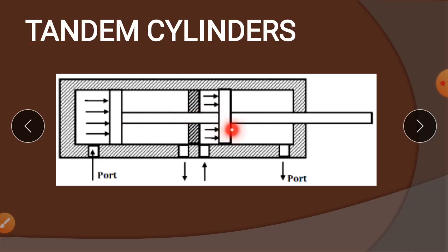So it is connected, one piston rod is connected to another piston rod, but there is some restriction between, there is some blocking between the two piston operations. Okay, so you can also say the two cylinders are going to be connected in this way. Each cylinder has two ports, one inlet and outlet. Similarly, this one has an inlet and outlet. It will interchange when the direction control valve directs the fluid.